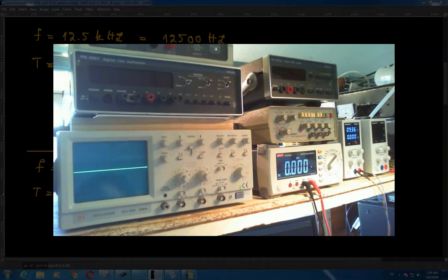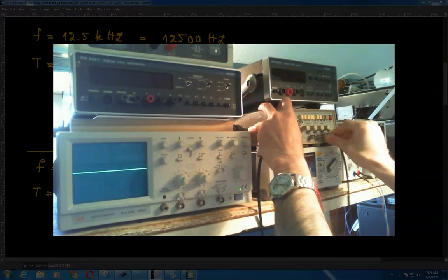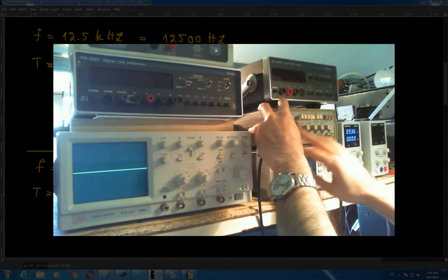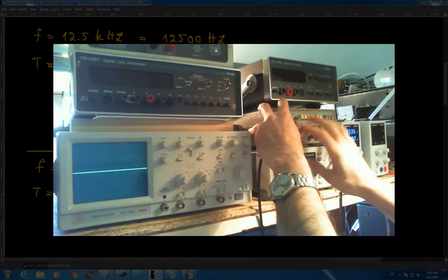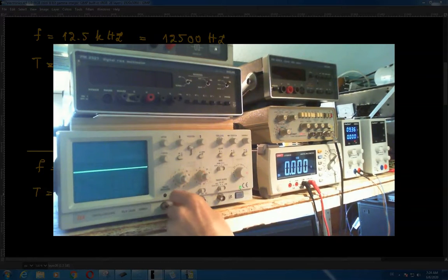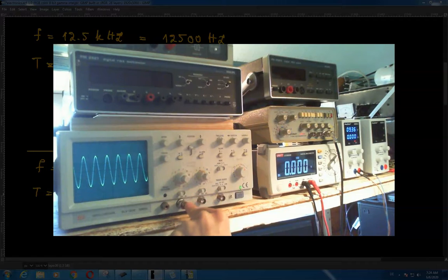Let's say that I connect this cable to the output of this signal generator and set it to, for example, a sine wave of 10k times 0.8, let's say 1 times, that's 10 kilohertz, right? And give it to the input of this oscilloscope over here, and that's going to be one of my inputs, essentially.